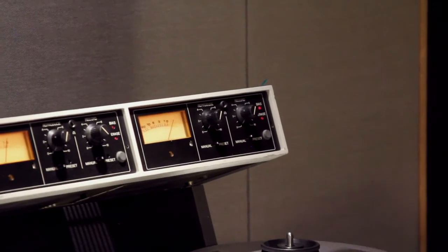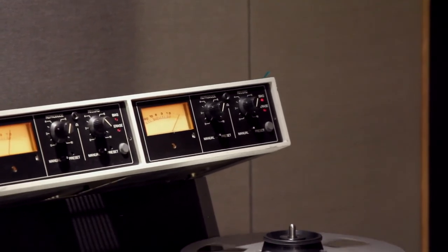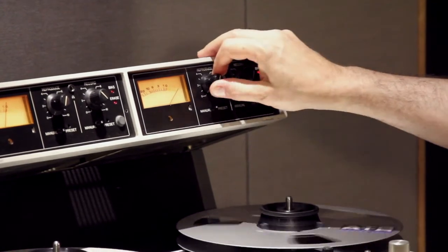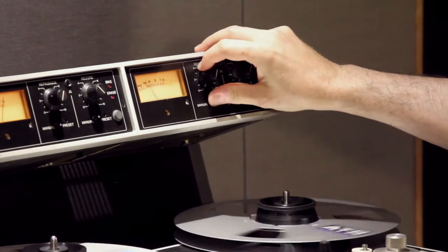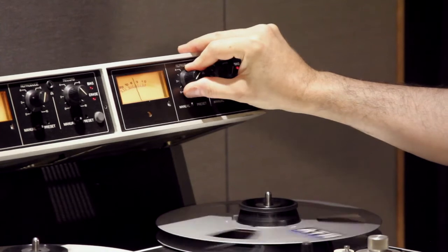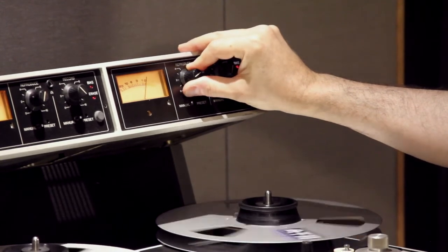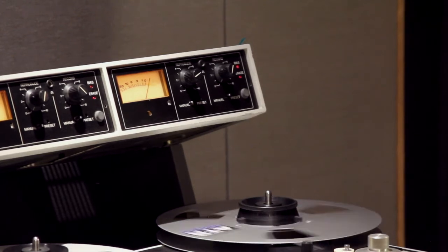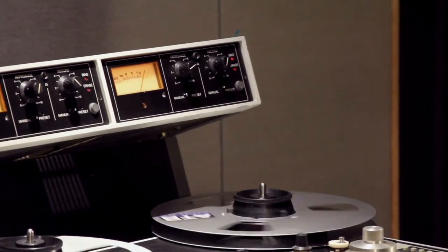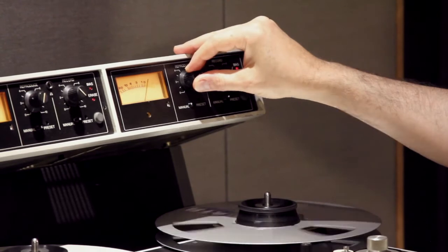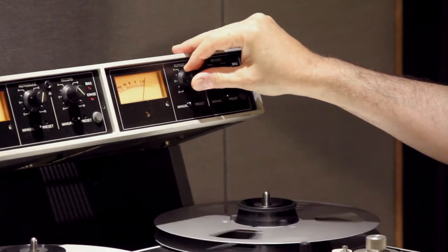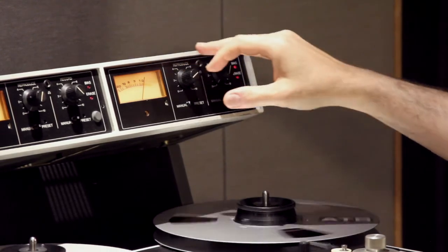Some machines don't have a master bias control available, or if they do, it's an internal adjustment. So in those cases, you just use the channel alignment pots and don't worry about it. Same deal here. I'm adjusting the non-calibrated output so that I can keep the peak signal at about 0 on the meter, and that allows me to find the minus 3 dB point easier.